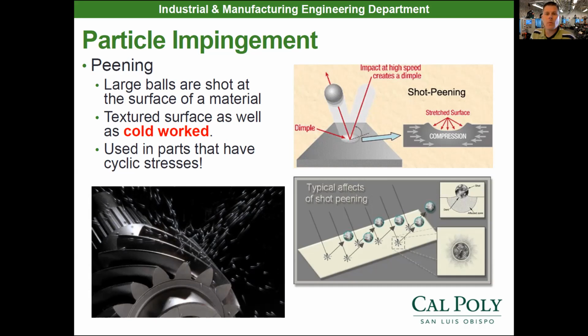What we would do is take the connecting rod of the engine and put it into a shot peening machine, which is a lot like a bead blasting booth, same thing, just different media. We would basically peen the rods by blasting those little beads against them. The beads would come and cold work the surface of the part, putting compressive stress in the part.